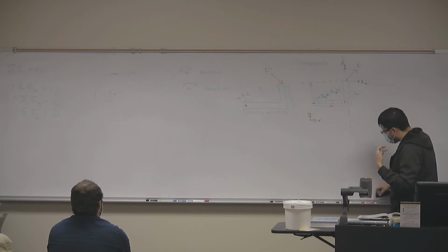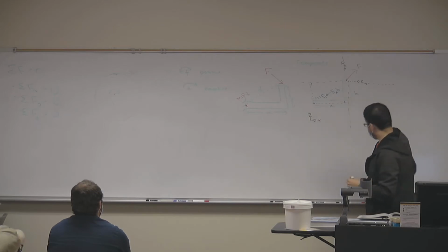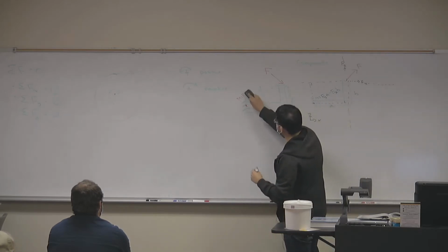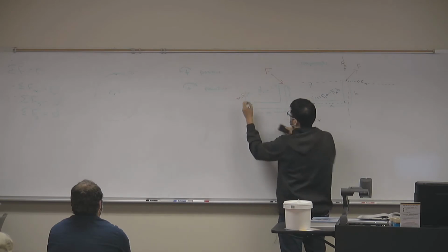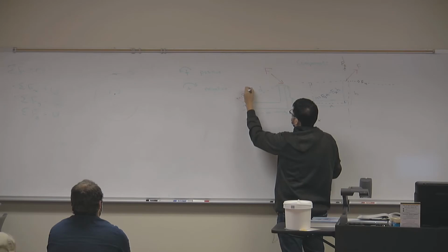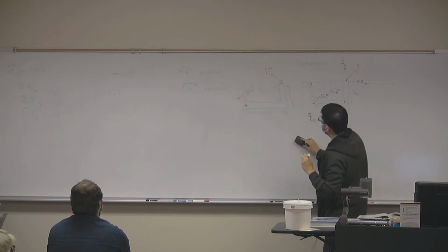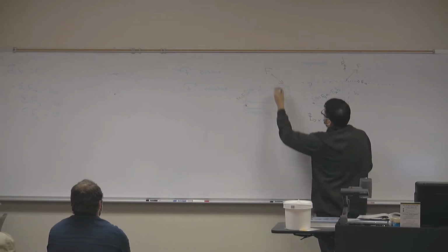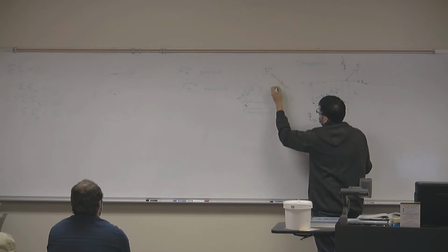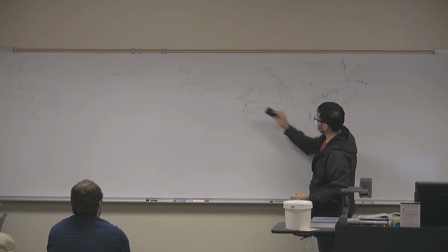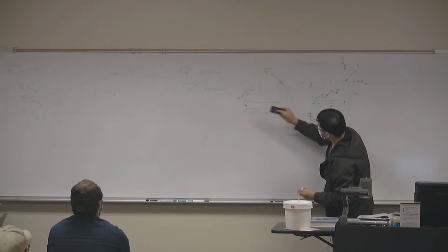So, different ways of calculating moment, right? I have my first method, which is simply force times the square root of a squared plus b squared. Now, this works because my force is acting at whatever angle from my point this triangle provides.